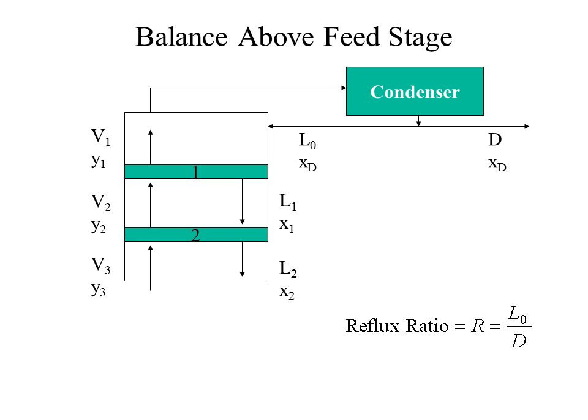The streams leave as L2 and V2, and the vapor stream coming from stage number 2 enters stage number 1, where it is mixed with the liquid coming from the condenser, known as the reflux. And this reflux has a flow rate of L0, and it also has the same composition as the distillate mole fraction X sub D. And we're going to define a reflux ratio labeled R as the ratio of this return stream, the reflux L0, divided by the distillate flow.